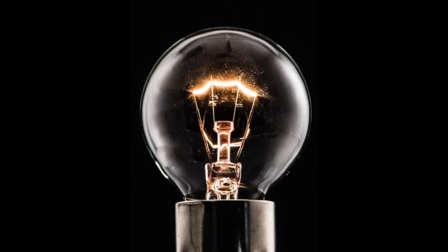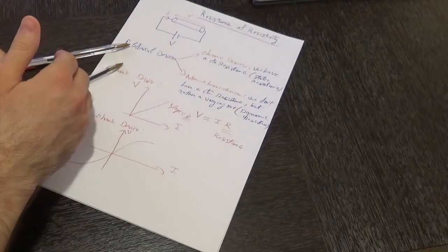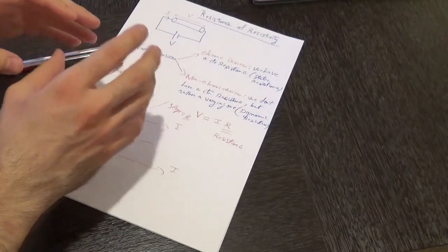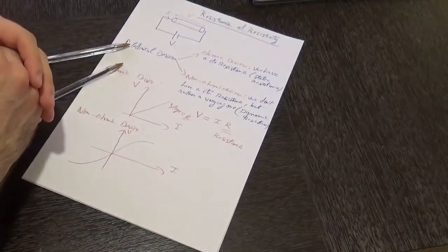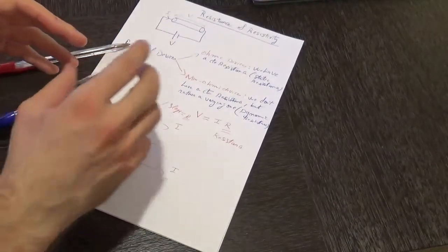So when the temperature of that filament starts to increase from room temperature and goes up, the intensity or the amount of light given off by that light bulb is going to vary as well, until we reach the maximum operating temperature of that filament, for which that light bulb would give off a constant light. However, that increase in temperature from room temperature to the maximum operating temperature is actually accompanied by an increase in resistance within that tungsten filament. So the resistance of the tungsten filament is increasing with every increase in temperature.